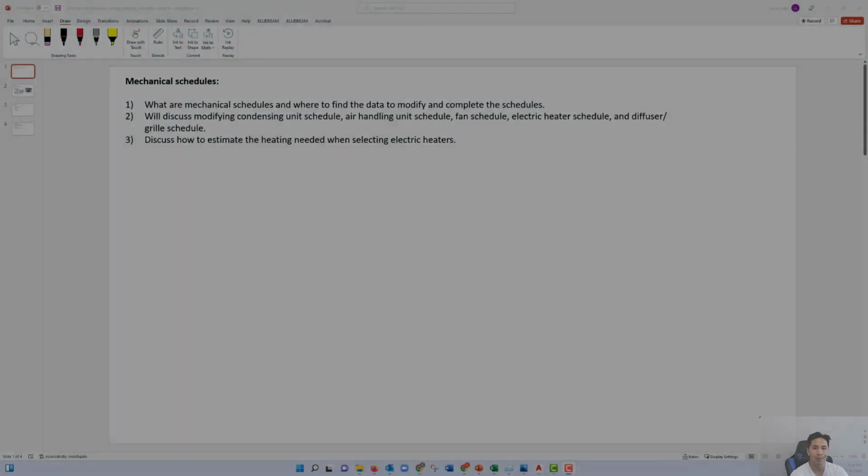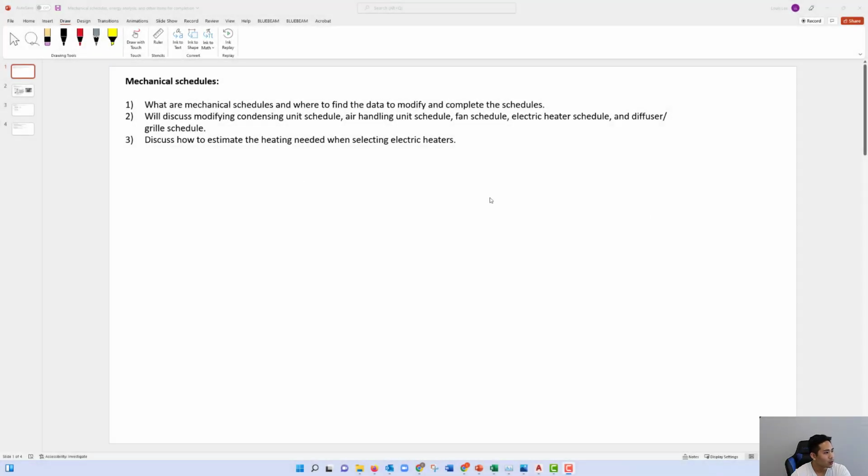Today's video, we're going to talk about mechanical schedules. So first is, what are mechanical schedules and where to find the data to modify and complete the schedules. Then we'll discuss modifying a few schedules, and they will include the condensing unit schedule, the air handling unit schedule, which are the indoor units, the fan schedule, which will include toilet exhaust and kitchen exhaust, electric heater schedule, and the diffuser and grill schedule.